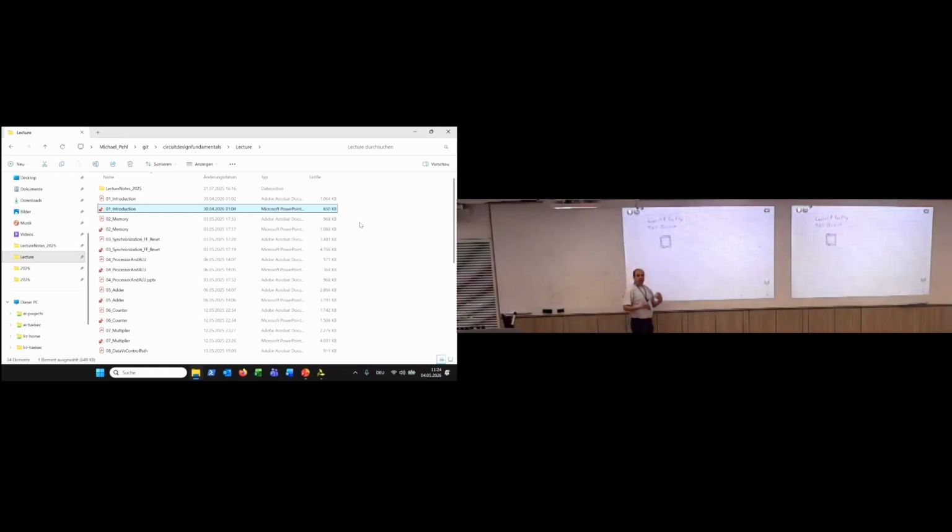Because later, when you manufacture the chip, you want to package this into some package, and you want to connect your internal chip to the external world. So you need to do the wiring from these internal pads to the pins of this black thing that you receive somewhere if you buy it. So this connection needs to be done. That's what we need the I/O ring for.